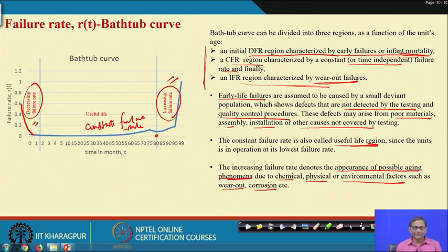So, what have we discussed? We have discussed hazard rate, and we related it to the failure density as well as reliability. And then we showed through a tutorial how the hazard rate is computed, and we also saw that the hazard rate is typically a bathtub curve, and you will get this bathtub curve if you have data for the system life cycle.